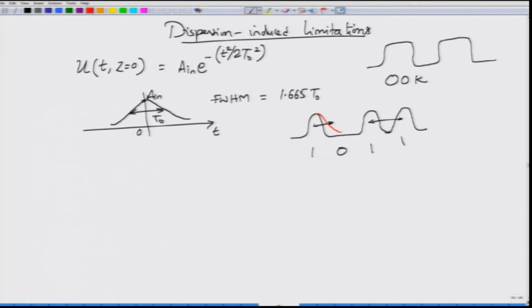What dispersion does is to expand the pulses around here, but when you expand these pulses you will see that the two start to merge together, and the overall pulse shape that you expect out of this bit sequence looks something like this. So, clearly these two are much more strongly influenced.